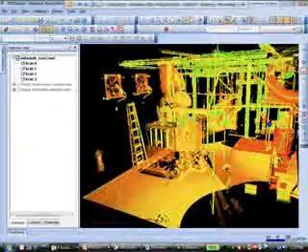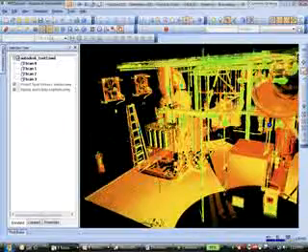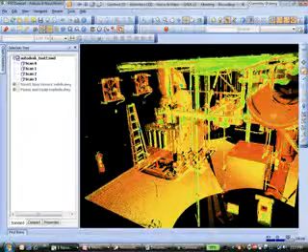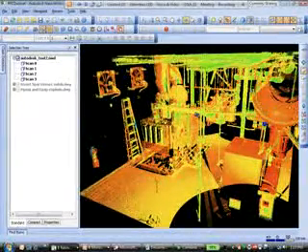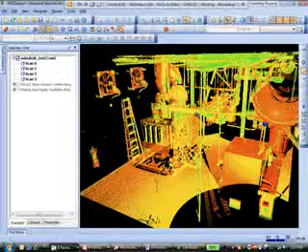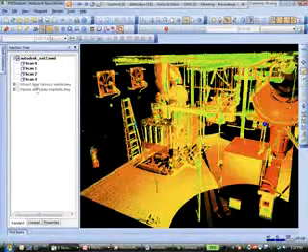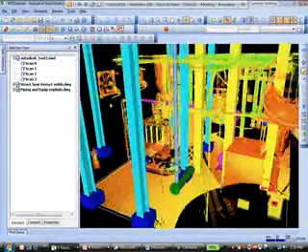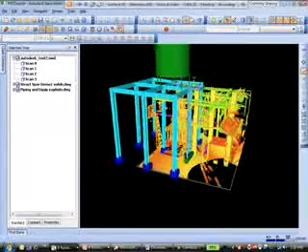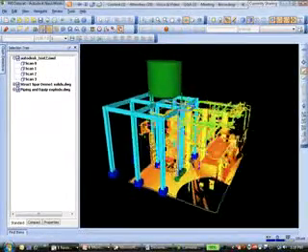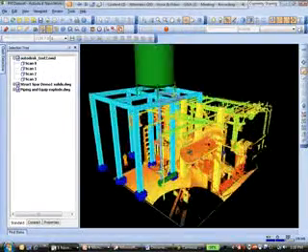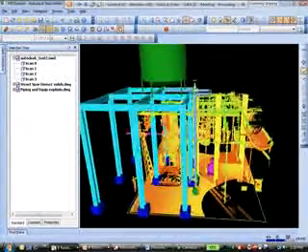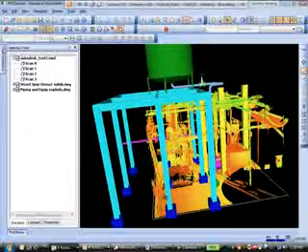One of the features from a construction and maintenance perspective is we're going to be working on an existing building, but we're going to be adding in some additional components. Utilizing this point cloud, we can now combine this with our digital models, and we can start looking at things such as clash detection. In this case, I'm going to bring in these other 2 components, and in doing so, now when I back out, we can see on screen we have the newer components which are going to be fit into this existing area. But using the clash detection feature inside of Navisworks, I can now determine if this particular design will fit within the parameters of this existing structure.